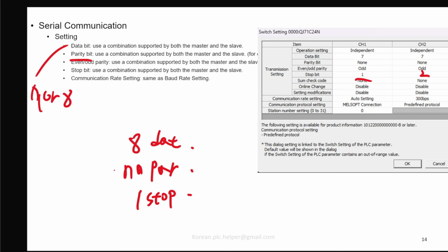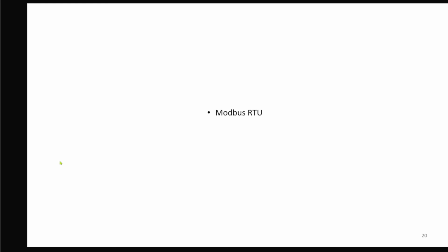This concludes the basic explanation of serial communication. Serial communication includes many additional applications beyond the topics explained today. Representative examples include Modbus RTU and Multi-Sys-Link. Serial communication is still widely used in factory automation applications. It is used with various devices including PLCs, inverters, measuring instruments, temperature controllers, and barcode readers. Therefore, I strongly recommend studying its basic principles and communication settings.